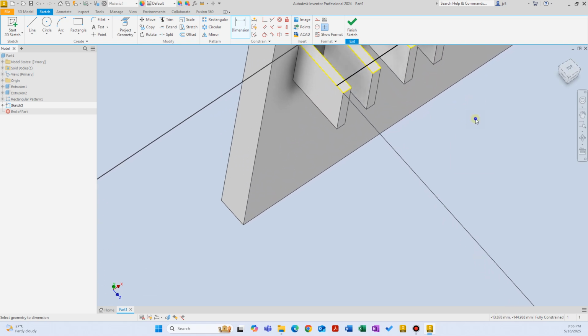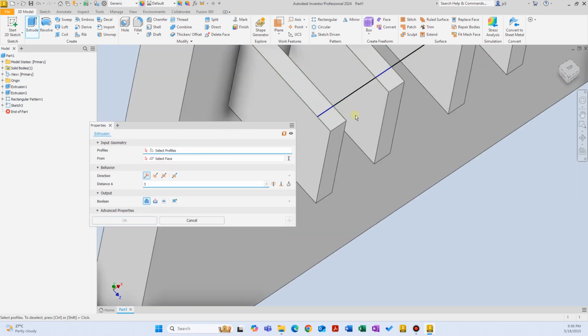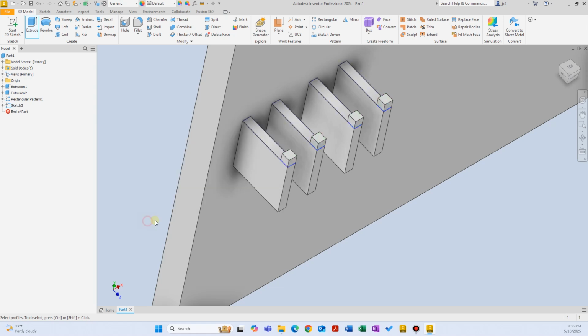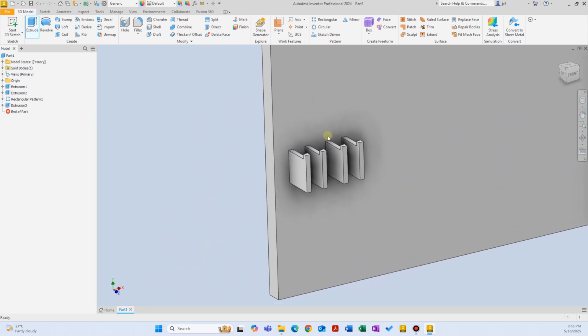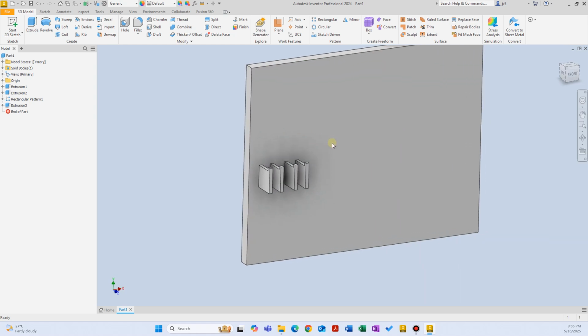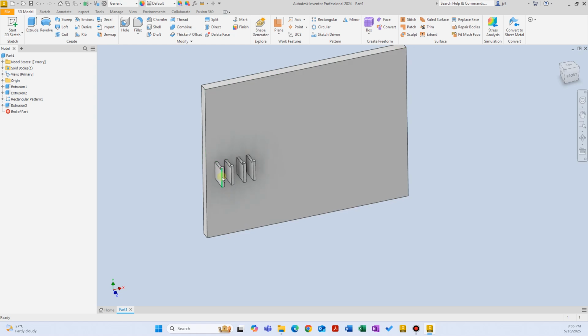Let's keep it consistent. Let's finish that 2D sketch and apply 3 millimeter extrusions to those little squares we created right here, here, here, here. Yeah, let's click OK. Right now it doesn't look that good, but we will add more fillets later and it's going to look pretty. It's going to look more aesthetically pleasing. And these are, let's say, our toothbrush holders.